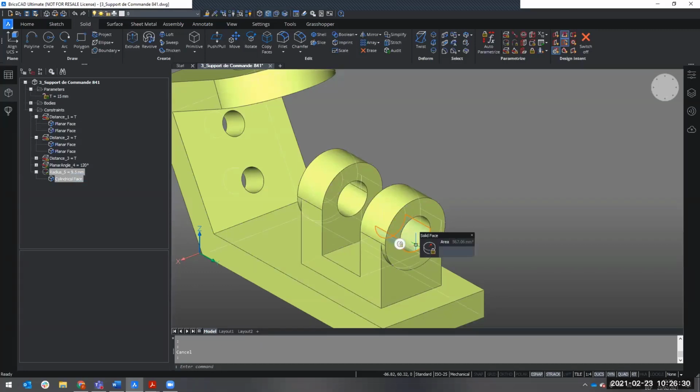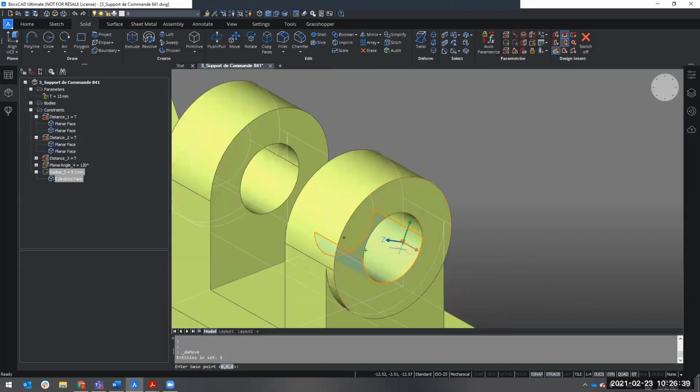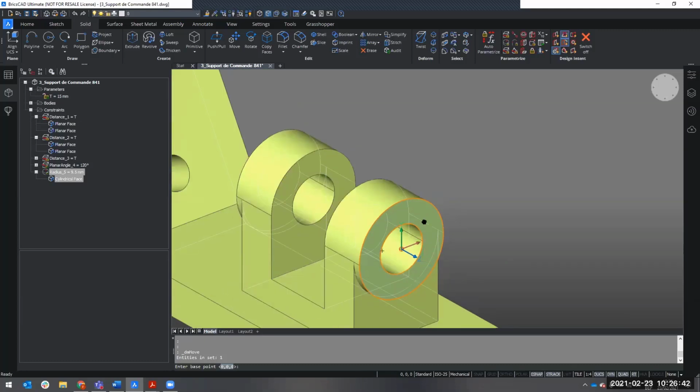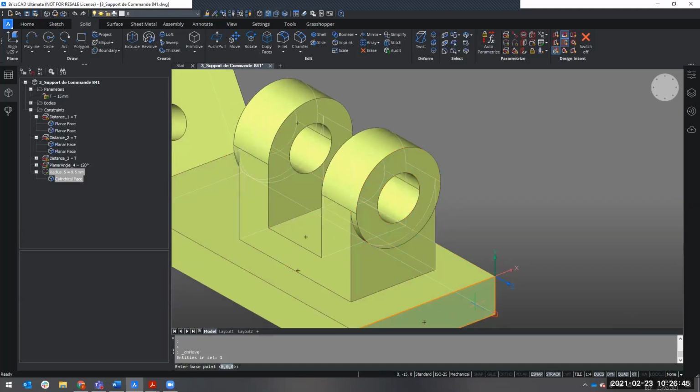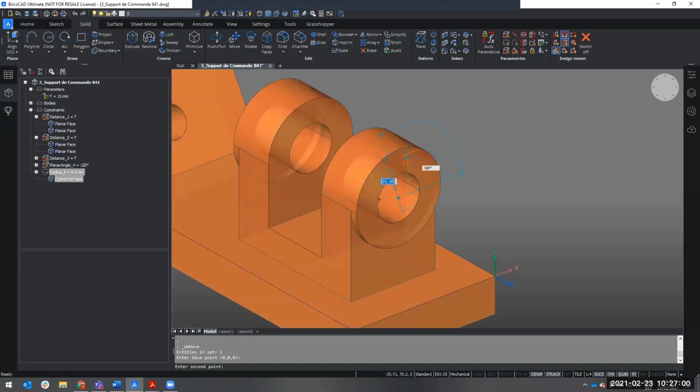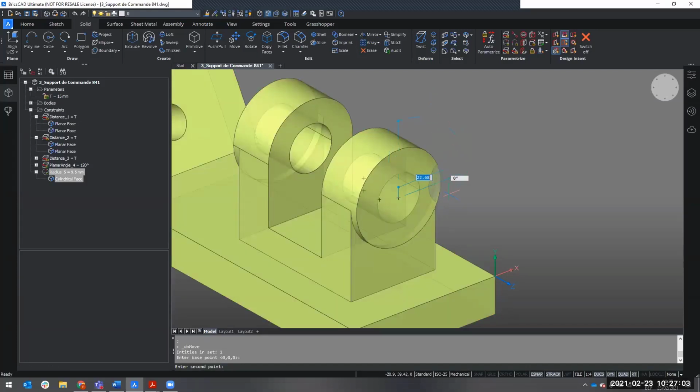But if I try to move this hole with the move command, so in the quad, I use the move command, then I can hover over a side here so that my dynamic UCS is shown with the y-axis upwards. Or with like nicely perpendicular axis, let's say. And if I then choose the geometric center and I try to move this one upwards by holding shift, or sideways by holding shift, you see that actually it's only one of the holes moving. It's not what I want. I actually want it to come along.